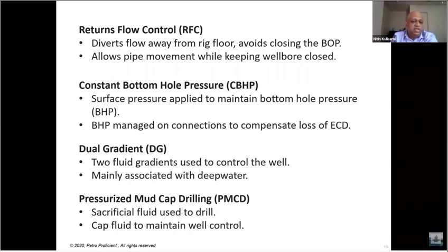So the last option is pressurized mud cap drilling. This is used in total loss, extreme loss situations, again in offshore environments, where you have fractured carbonate reservoirs, where these fractures are so big that you lose all your drilling fluid.